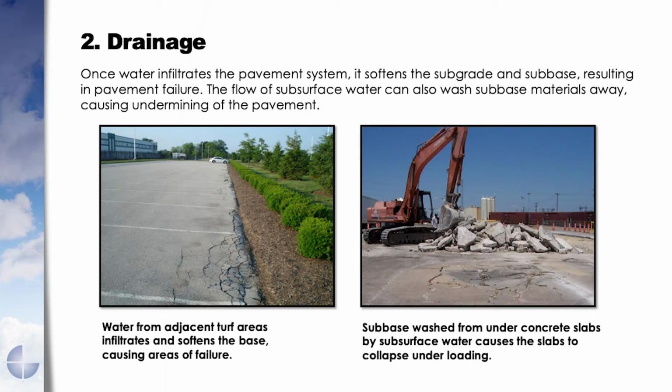And then the water is sweeping back underneath the pavement into the crushed stone, which is more porous than the dirt in the landscape island, softening up that edge. And then, of course, the cars parked right up on the edge of that pavement, causing this damage. So this premature failure was caused directly by poor drainage along the edge of the pavement. So that would have to be taken care of before any patching or reconstruction would be done.